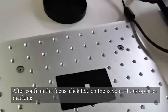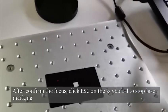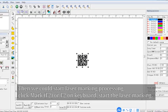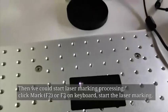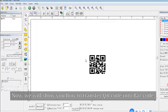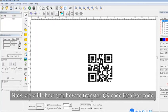After confirming the focus, press ESC on the keyboard to stop laser marking. Then, cancel the continuous parts. We could start laser marking processing. Click Mark, F2, or F2 on the keyboard. Start the laser marking. Now, we will show you how to transfer QR code into barcode.